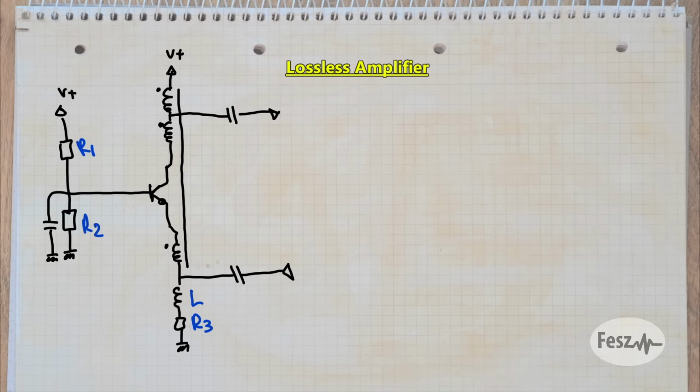This is usually defined as having a turns ratio of 1 to n to m, where 1 is the number of turns in the emitter circuit, and n and m refer to the collector circuit and represent multiples of the turns in the emitter. Then the circuit is finished off with some capacitors, one for stabilizing the base voltage, and two for coupling the signal into and out of the amplifier.